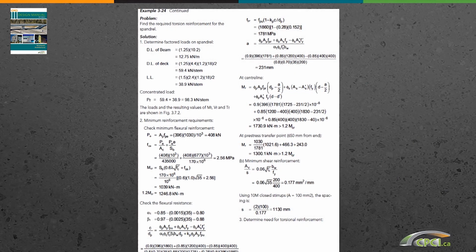This is new and changed. This example has been revised from last time. Last time we did it in a fast way, and it wasn't that correct. But this one here is done the proper way. Essentially, we again have sections that we have to go through. Number one, we need to know whether minimum reinforcement has been achieved. We find that minimum reinforcement is achieved.